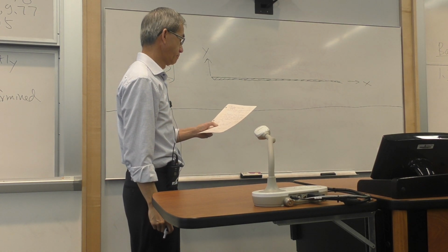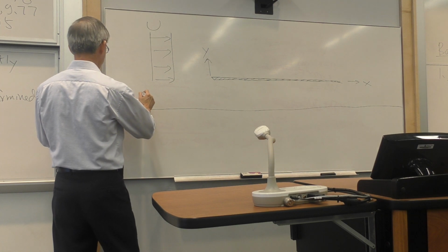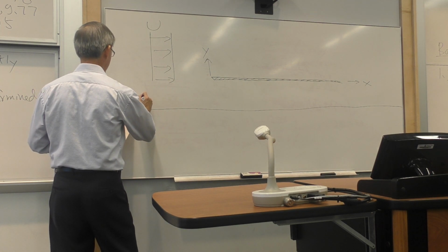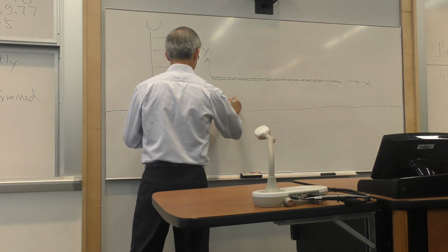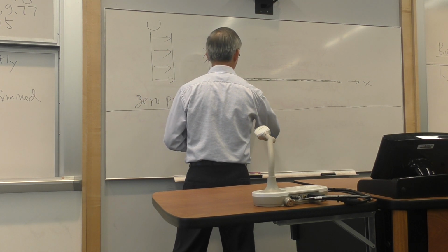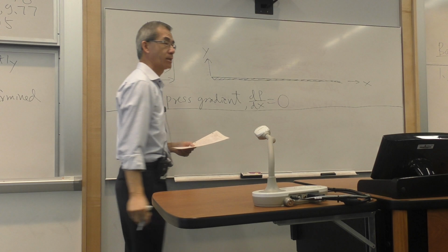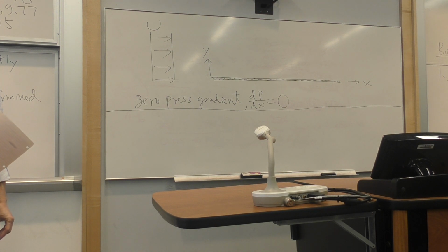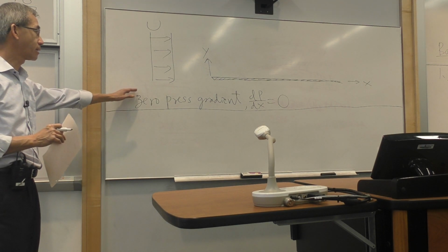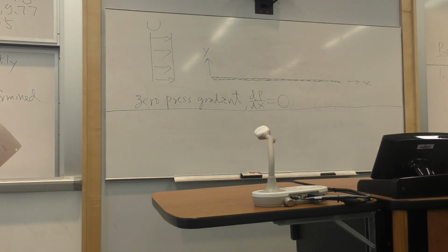And what we find, based on the following assumption of zero pressure gradient. That's the simplest case we'll start with, meaning as I go down in x, there's no pressure change. dP/dx is zero. And later on, you'll see why this is an important consideration and helps simplify our analysis using the viscous equations of motion. So it's somewhat of a baby step in analyzing some much more complex problems.